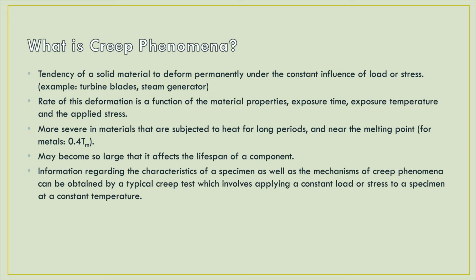It can be described as the tendency of a solid material to slowly deform permanently under the constant influence of mechanical stresses. The rate of this deformation is a function of the material properties, exposure time, exposure temperature, and the applied stress. Creep is more severe in materials that are subjected to heat for long periods and nearer to the melting point. For metals, that would be at about 0.4 times the melting temperature. This means that creep always increases with temperature.